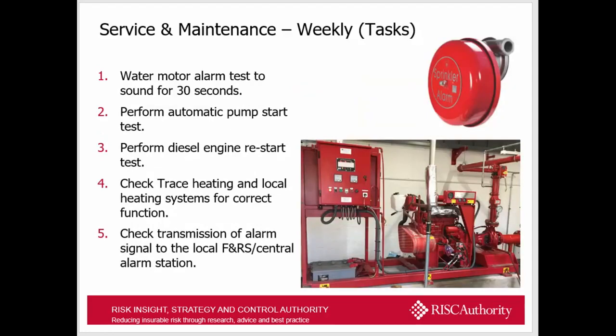Service and maintenance tasks. Now these are things that you actually physically have to do. So we have to run the water alarm gong for a period of 30 seconds. We have to perform an automatic start on the pump's spark test. We do a diesel engine restart test. Check the trace heating, local heating systems for correct